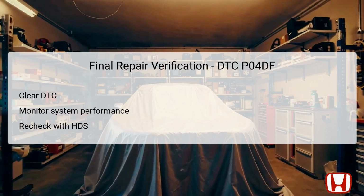Initially, clear the DTC from the vehicle's onboard computer using the HDS. Subsequently, take the vehicle for a test drive under various conditions to ensure system functionality and to observe if any symptoms re-emerge. Monitoring the performance of the EVAP system during the test is essential in confirming that the repairs address the fault effectively. Post-test, recheck with the HDS to assess whether any new DTCs have been logged or if P04DF has reappeared. This verification process is vital for certifying that the vehicle is in optimal running condition.